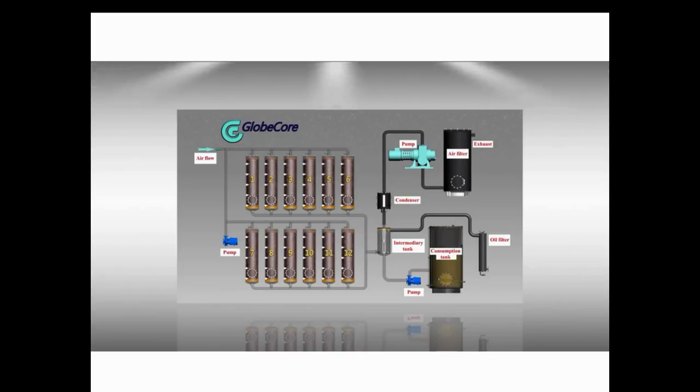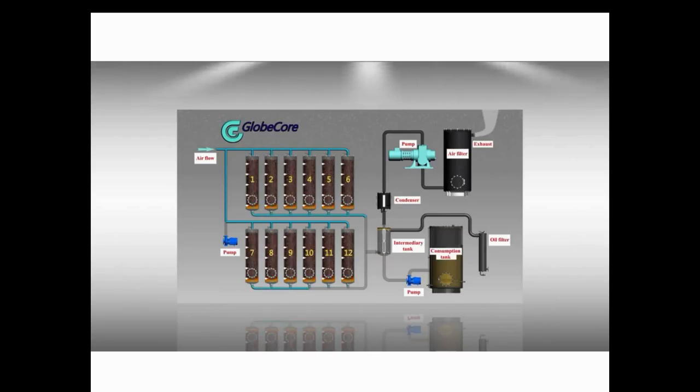The regeneration plant cleans Fuller's earth on its own, separates sludged oil and gives treated oil. So the next day you can use the same Fuller's earth to process oil. Now you see how cost saving comes in, as we don't lose oil in saturated Fuller's earth for disposal and keep using the same Fuller's earth for 300 cycles.